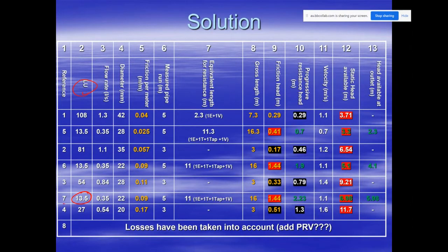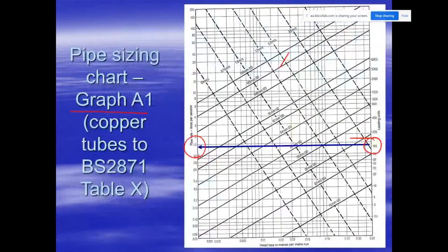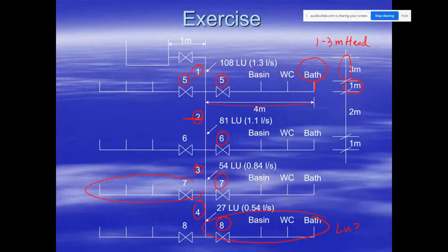So for example, pipe reference 7 should be 15.8 loading units, same as 6, 5 or whatever. Understand? This is the branch pipe. So that means the branch pipe diameter for 5 equals 6 equals 7 equals 8. Am I correct? Am I correct? Yes or no?